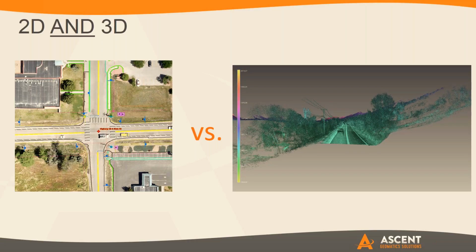So just on the left as an example, there's an orthomosaic that we actually collected, and then the standard, in this case it's a DOT project, so we were using InRoads, and it's all your normal levels within MicroStation that you'd want. We'll extract that out, deliver a field look, deliver whatever product it is, and then on the back end, we have the right side example of the really robust three-dimensional environment that we can go and extract more from if more is needed after the fact. So we extract out what's needed at the parameters of the project as it was scoped, and then we have additional information available for when someone all of a sudden says, hey, let's expand it a few hundred feet more in one direction.